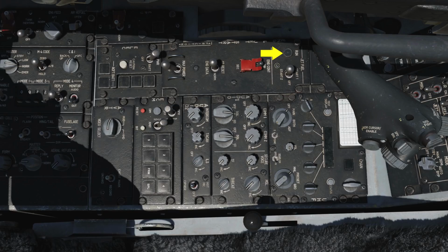Next to the switch is a JFS run light that illuminates within 30 seconds after JFS initiation. Below is the guarded switch for the primary and secondary engine control modes. You normally have this in primary mode unless you run into a failure with the engine's digital electric control, in which case you can select secondary mode, or you'll have to cycle the engine to restart it after a flameout. Note that in secondary mode you have no afterburner.